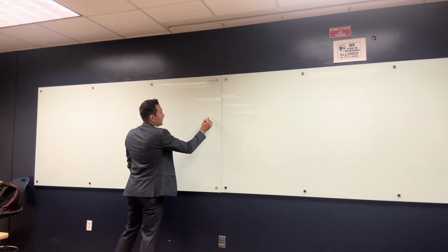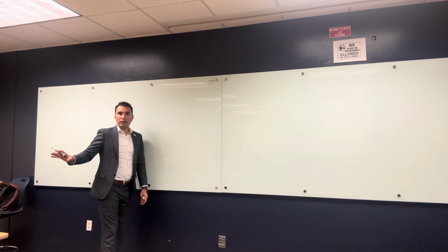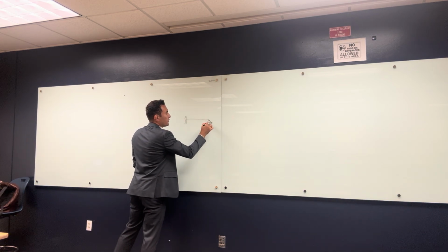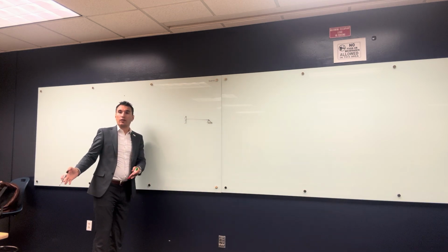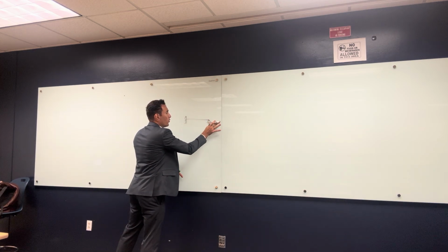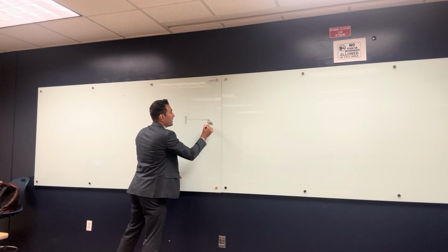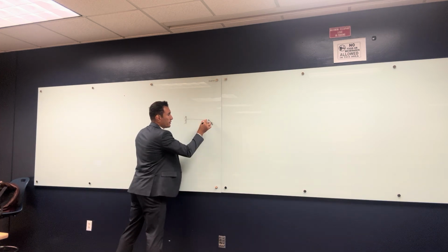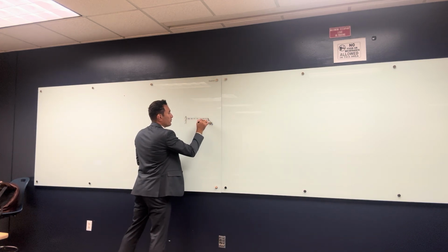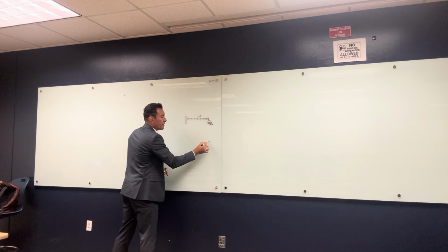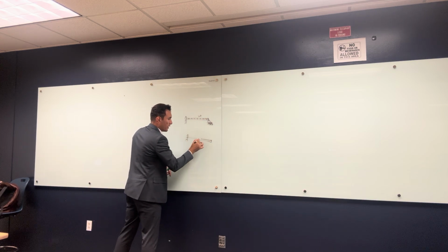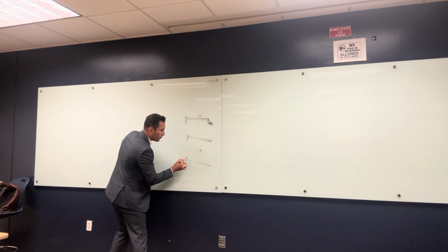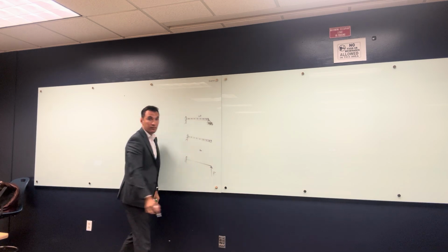Okay, so the flexibility method is a method to solve an indeterminate structure, and as I said last time, an indeterminate structure is going to be something like this. If it's a cantilever, I will be able to solve it, but it's not a cantilever. There's a hinge or a roller here, okay? So I can't solve it, but we can make this into two beams. If it has this load W, I can say that this beam is a cantilever, plus a beam like this that has a reaction F, right?